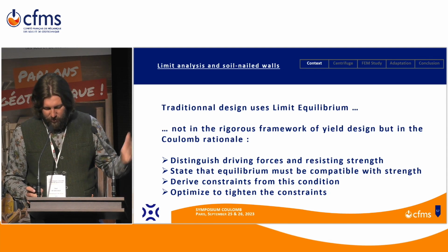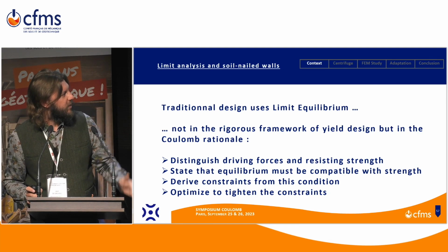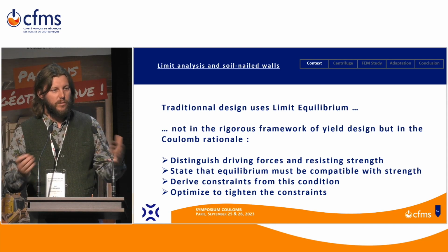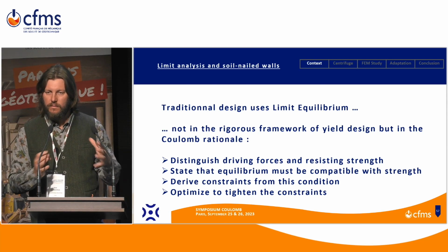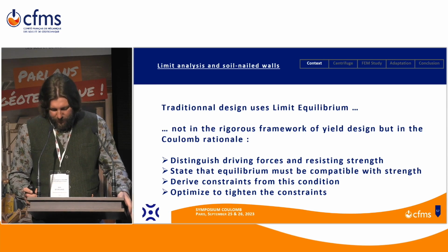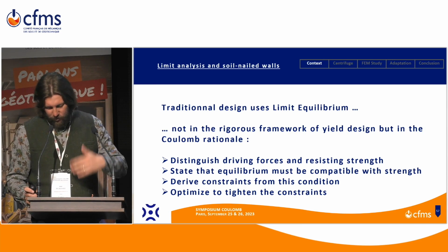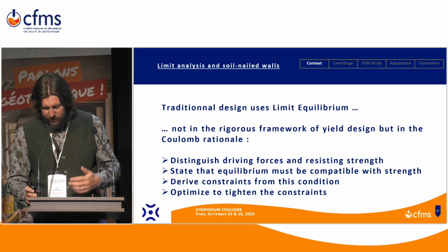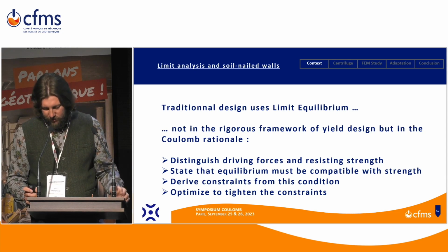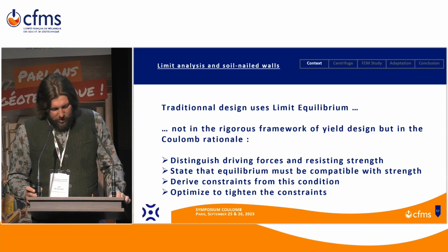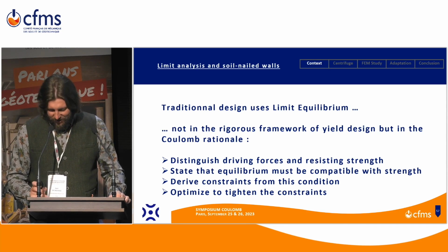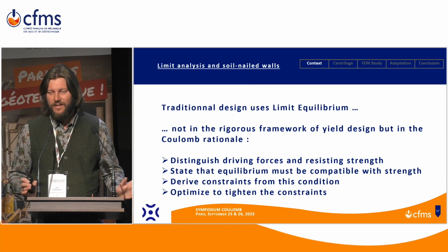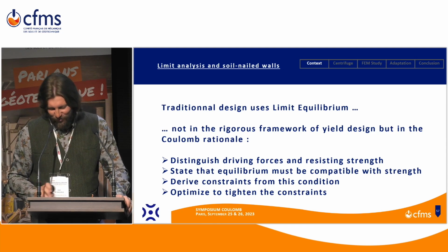Then you write the equilibrium, you say it must be compatible with the strengths, it gives you constraints, and in the end you have an optimization process to tighten the constraints. For example, you will look at different failure surfaces or different mobilizations of the nails. So as I said, it's not rigorously yield design, but still it fits, I think, in a Coulomb symposium.